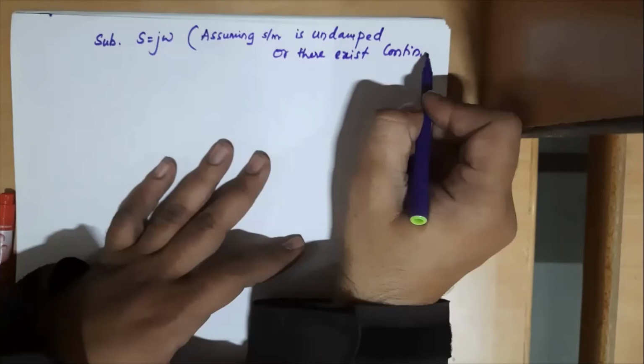So the story goes like that. If you have purely imaginary roots, the system is undamped. At the point of intersection on the imaginary axis in a root locus, the roots are purely imaginary, therefore at that particular gain the system is undamped.